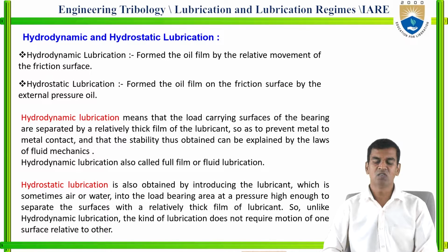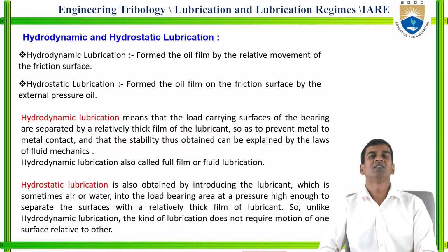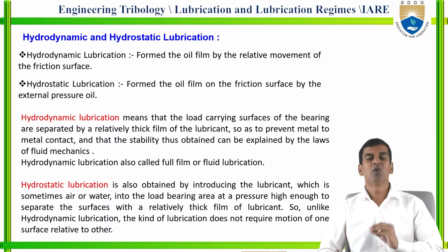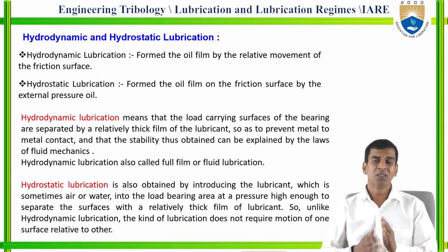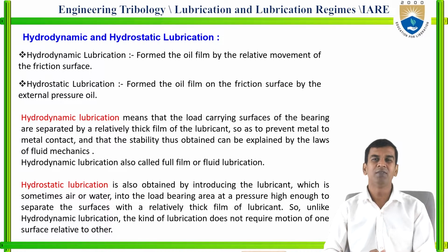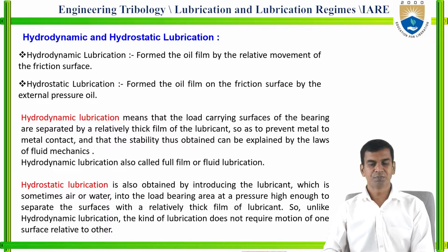Hydrodynamic lubrication is also called full film or fluid film lubrication. It is a thick film lubrication, where there is a large amount of clearance between the two mating surfaces which are in contact. That large clearance is filled with fluid, so the fluid is available in full amount. Because of that, it is called full film or fluid film lubrication.